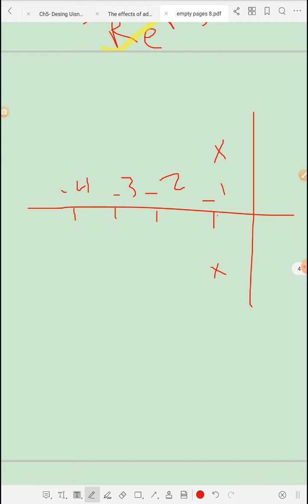I am assuming that the real part of this pair of closed loop poles is equal to -1, and assume that there is another pair of closed loop poles located here. If we pay attention to the real part of that pair, it's around -2. So the ratio between -2 over -1 is less than 4.